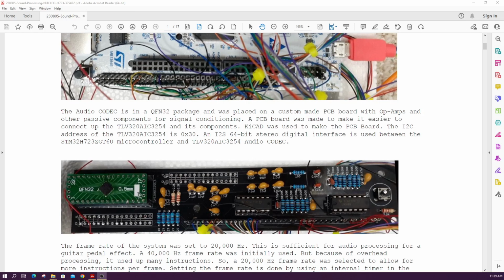is a buffer. Now I also have a reset switch on this that I don't normally press, but it's helpful to have in troubleshooting. Sometimes you have to reset this. So if you do reset this, you have to run the processor one time to send the instructions to set up the registers of this audio codec.